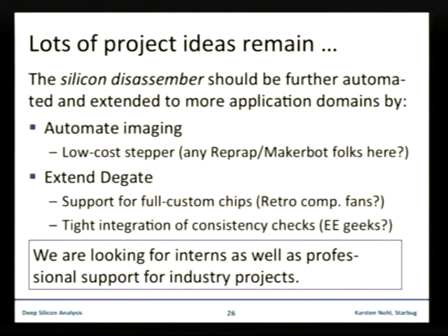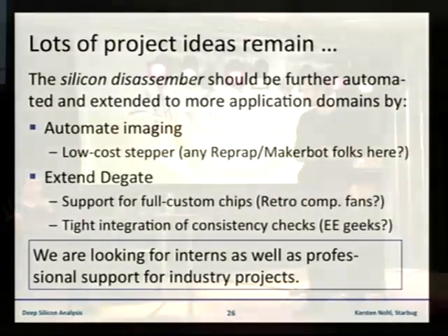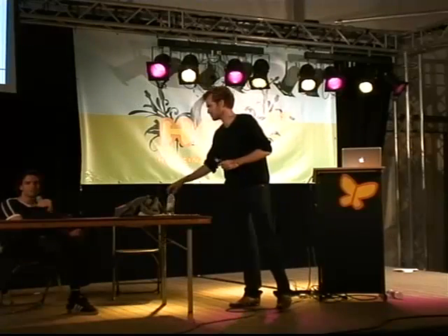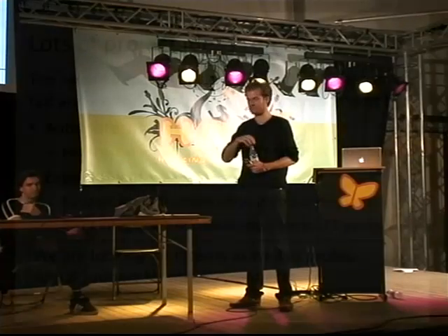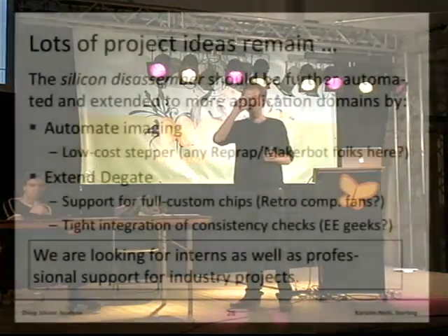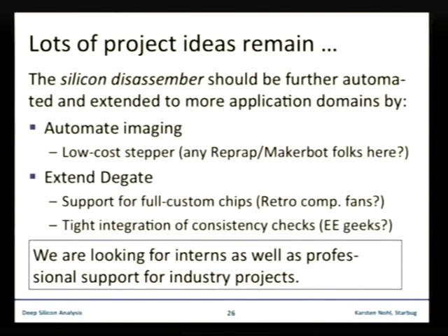And so this would be one construction. So you can move a lever from left to right. And so you make this 2 times, and so you have an XY drive that has cylindrical coordinates. So you have to do a little bit of calculus. But it's a cheap solution. Yeah, it should work, but we need a really low resolution, so about some microns. But the hard drive makes this. Have you seen a 50 gigabyte hard disk? It has a very fine resolution. Okay. Because a voice coil has an indefinitely fine resolution.